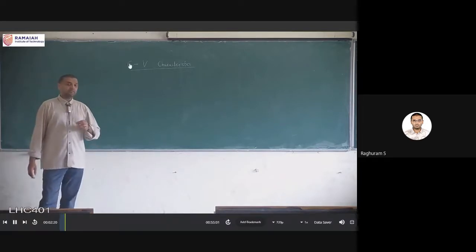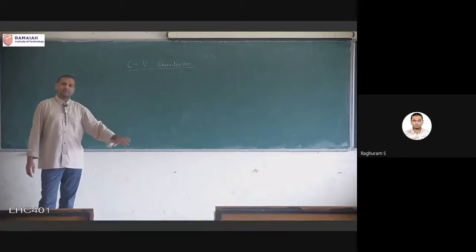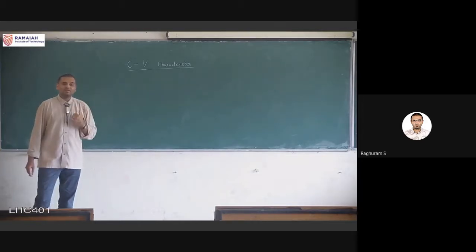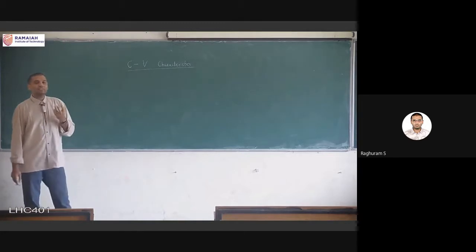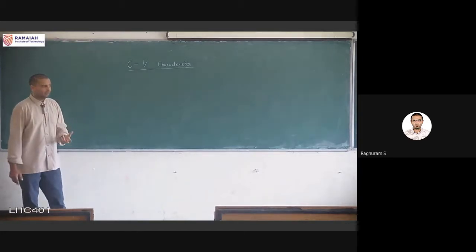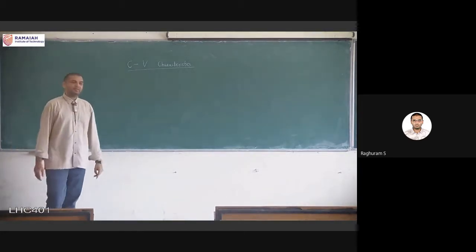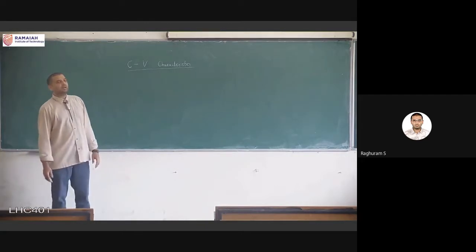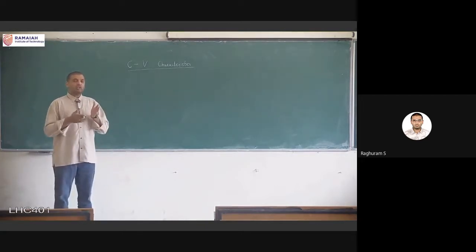But this is very important because this determines the speed of the transistor also. We talked about current as determining the speed. That is a good thing: if the current is high, speed is good. Here, capacitance is a bad thing. Every transistor is associated with a certain amount of capacitance, and one of the properties of capacitance is that it doesn't allow voltage to change instantaneously.